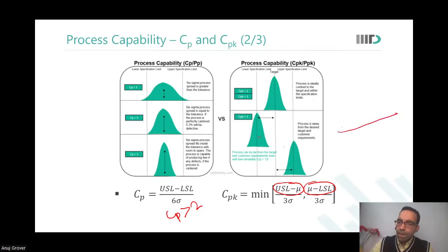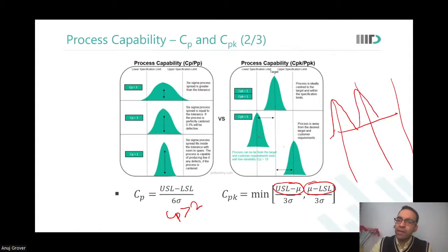Sir, the upper spec limit would be the value corresponding to minus 6 sigma or plus 6 sigma, if it was centered, right? What is the meaning of spec limit? Tell me, what do you understand by spec limit? If you do not understand that, how will you understand what I am talking about? What is spec limit? Upper and lower bounds for my design for any parameter. If you violate these bounds, then I would reject the die.